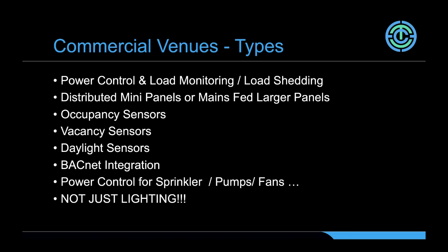BACnet integration is important in commercial venues. When we're dealing with, say, parking garages, BACnet integration to the building BMS gives them status monitoring of the power control or lighting circuits in the parking facilities. There's quite a number of facilities now that have occupancy sensors on each of the floors to give them occupancy status of not only parking spaces, but people in the stairwell corridors and whatnot, and we're offering that information back over to BACnet, which is interfaced with the security systems and so on and so forth.